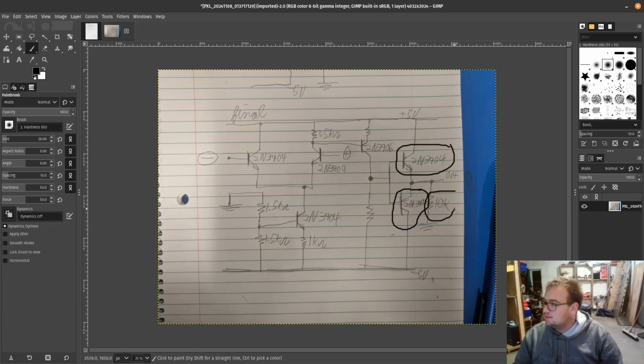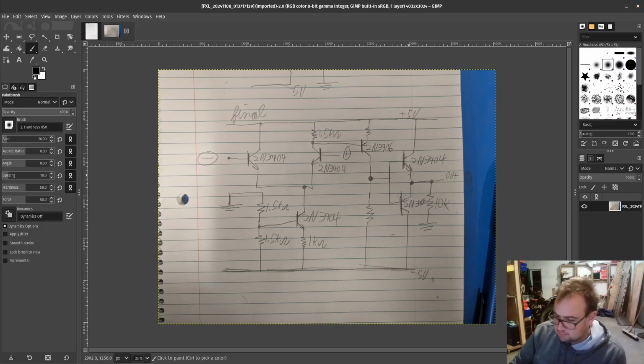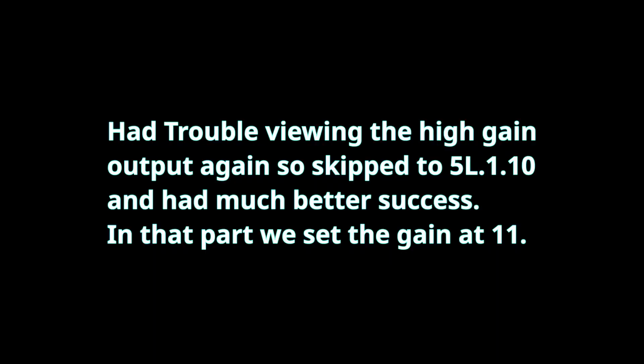And then I'll put in this 10K resistor. That is the final circuit that they made. You can see that final circuit on page 217. At the end of it, it says feed a small sine wave differential signal to the input at a low frequency, 1 kilohertz or under. Watch input and output of this stage. So we will do that.